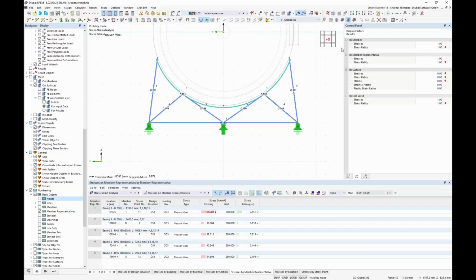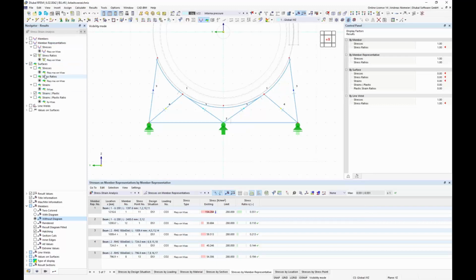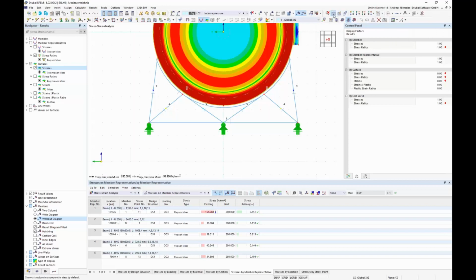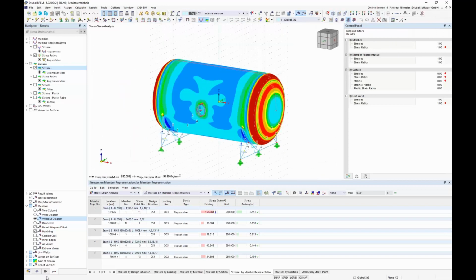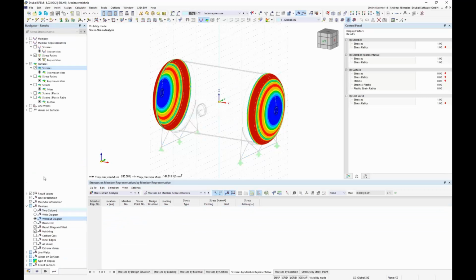For the surfaces, right, let's say now go back to surfaces. Here we have stresses. We start from stresses. You have here the structure, and maybe you can use here your selection according thicknesses, vaulted head like we started. You can bring in here the maximum and minimum stress by values on surfaces, extremes, and let's print here maybe the stress plot, what is on the yield strength.